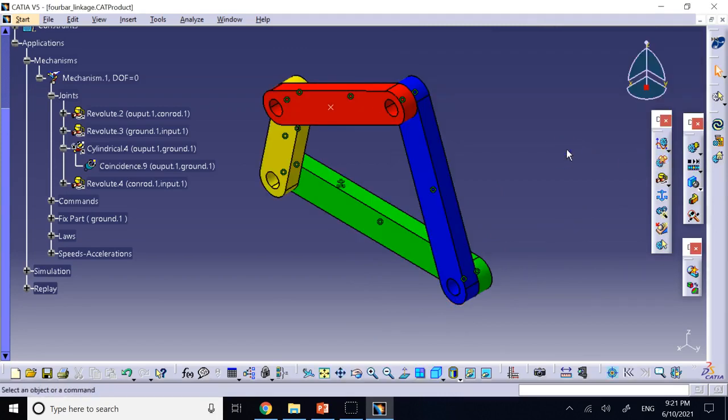Okay, so by choosing the appropriate input, output, making sure the degree of freedom of the mechanism is 0 after providing input, and it tells you that the mechanism can now be simulated, then you can do manual simulation, create videos, do the tracing, swept volume, create a law, do the speed, acceleration, position, or anything else, plots of them versus each other or versus time, customized plots.